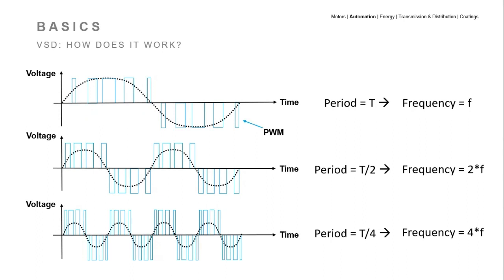Let's now zoom in the VFD's last stage to understand better its operation. The following waveform depicts the behavior when varying the width of the PWM pulses. This curve shows a signal of a frequency f where the pulses have predetermined widths to recreate a sinusoidal waveform. The wider the pulse, the higher is the voltage in a given curve. On the contrary, the thinner the pulse, the lower is the voltage delivered. What makes a pulse wider or thinner is the duty cycle of the switching device, in this case, the IGBT.